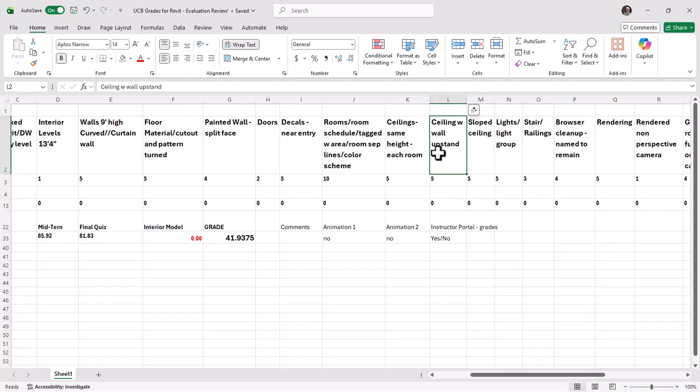All of the walls were unconstrained, so they were dimensions from the bottom of level 1 to the height of the wall from level 1, not using levels to, say, attach it to level 2, but having everything built off of a level and giving it the actual height the wall is going to be in a project. I looked for a sloped ceiling between conference rooms, and that was using the slope arrow to give it an angle. I looked for light groups.